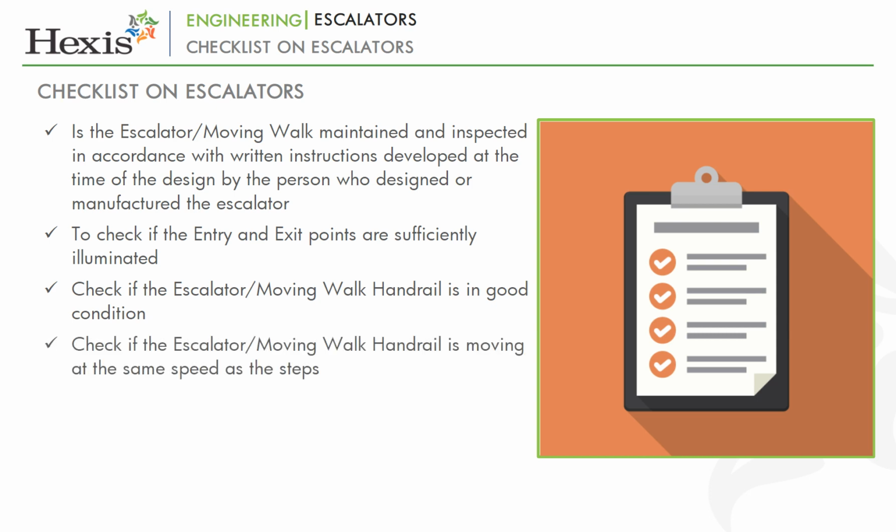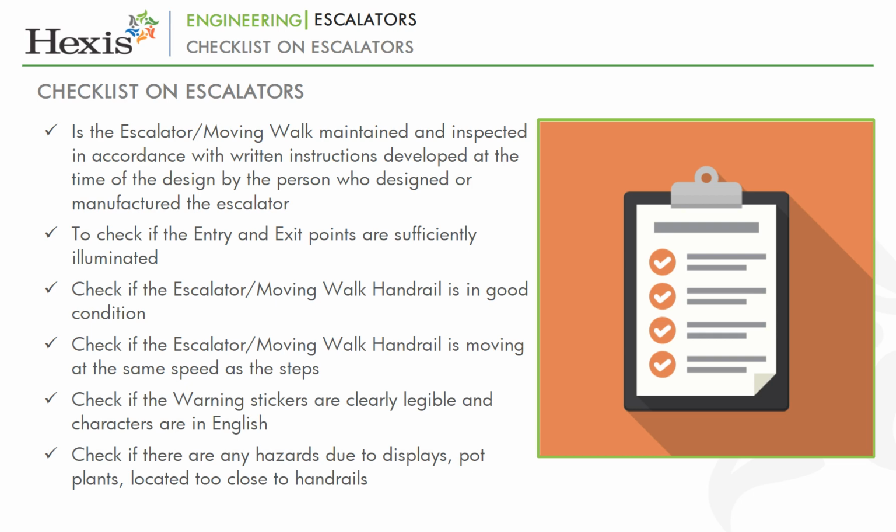Check if the escalator or moving walk handrail is moving at the same speed as the steps. Check if the warning stickers are clearly legible and characters are in English. Check if there are any hazards due to displays, pot plants located too close to handrails.